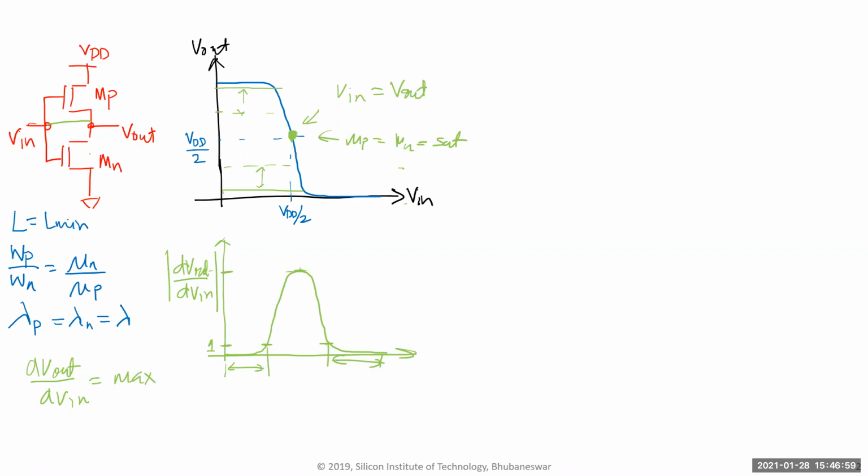But it's still not good for me, because if I short it, then how do I give a signal? Because all it's doing is VDD by 2. It's a nice bias for you. It's just a voltage divider for you. It'll do a VDD by 2 and give it to you, but it's not good for me to give a signal to it, right? So what do I do?